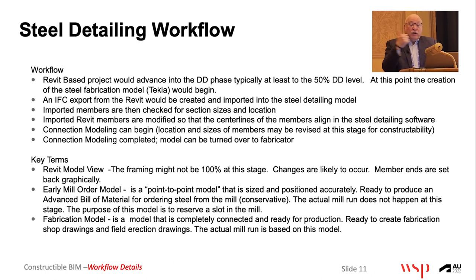So when we turn it over to the Tekla modelers, the first thing we get back is, where's the steel? Can I believe the Revit model? If it says it's 10 feet from wherever, can I believe it? And I say, no, you have to have the dimension on the drawing, and there's no dimension on the drawing. I won't get into that.